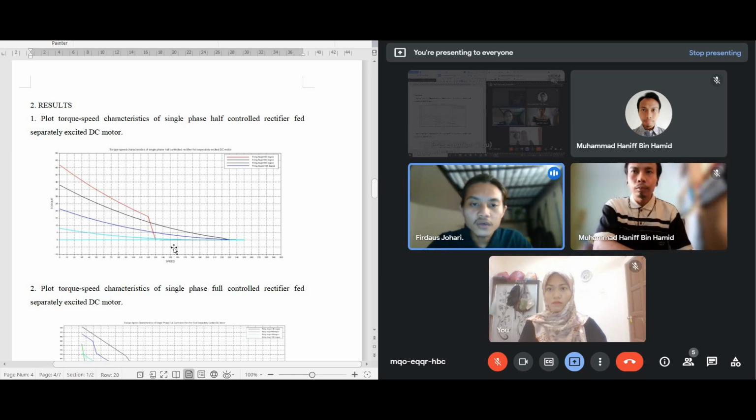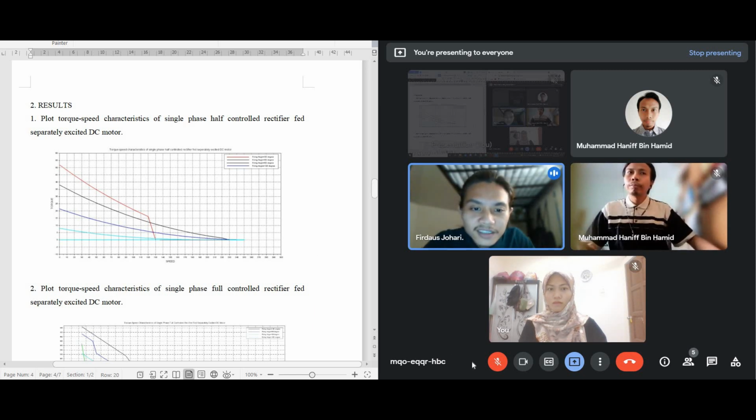If an additional load torque is applied, the motor speed momentarily decreases and the speed error increases, which increases the control signal. The control signal increases the converter output voltage, and the increase in the motor armature voltage develops more torque to restore the speed of the motor.